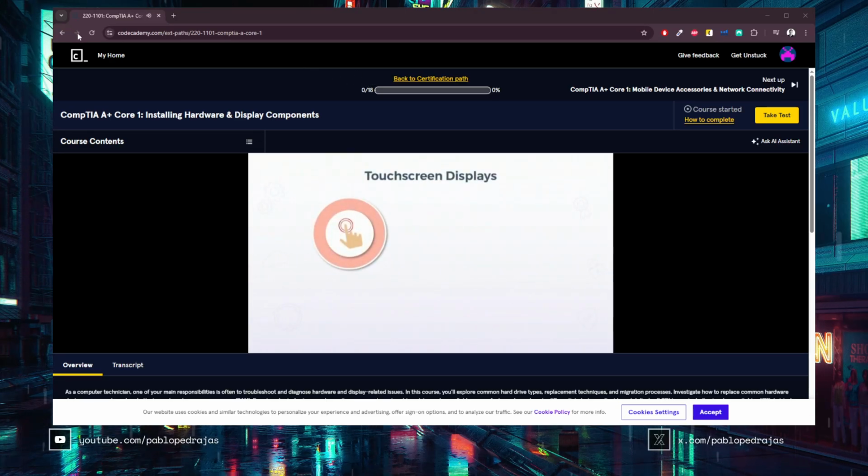Another key component of a mobile display is of course the touchscreen capability, and these are certainly available on many laptops, but in today's environment, it's much more of a concern when using our phones and tablets. The underlying component of a touchscreen is known as a digitizer, which interprets the taps of our fingers into digital commands that can be accepted as input. Virtually every touchscreen these days accepts your finger as the input mechanism, but many devices also support a stylus, or a digital pen, if you will, which is far more accurate, particularly if you need to draw, sketch, or use